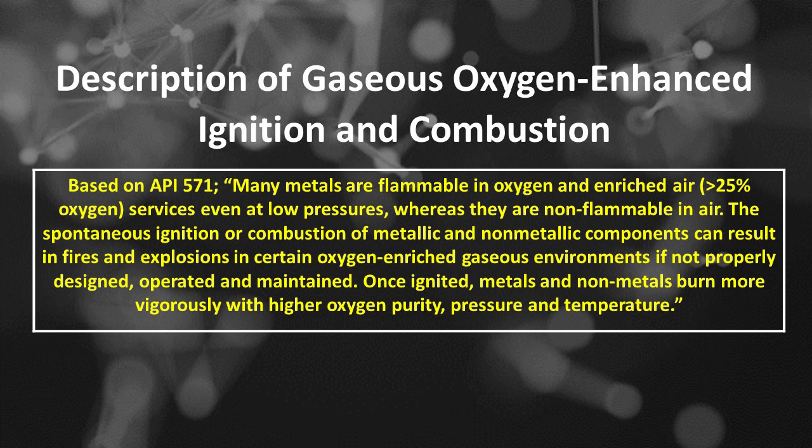Many metals are flammable in oxygen and enriched air, greater than 25% oxygen, even at low pressures, whereas they are non-flammable in air. The spontaneous ignition or combustion of metallic and nonmetallic components can result in fires and explosions in certain oxygen-enriched gaseous environments if not properly designed, operated, and maintained. Once ignited, metals and nonmetals burn more vigorously with higher oxygen purity, pressure, and temperature.